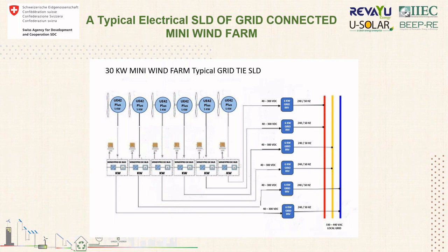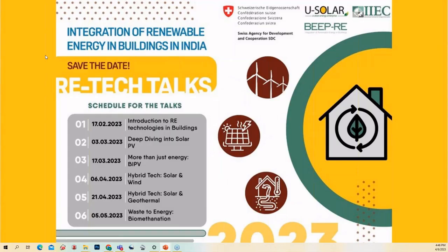But with the new controllers that we have in the making, probably we can have a single inverter for feeding solar as well as wind. It will be a bit on the expensive side because it will have to incorporate both parts, but it is still some distance away. So as of now, parallel, not joined to the same inverter. That's the answer.